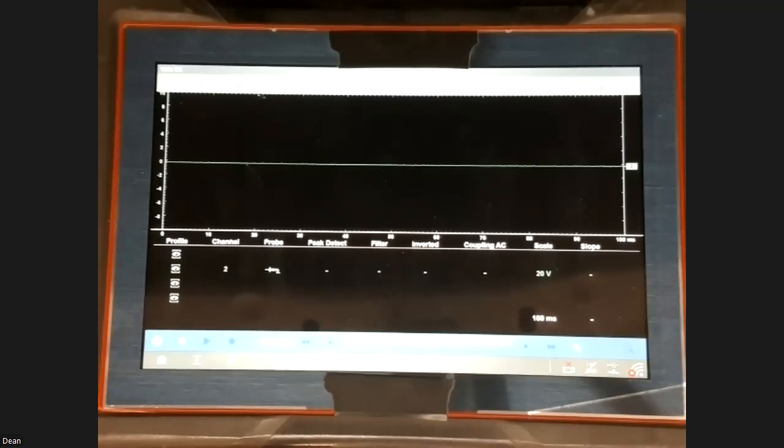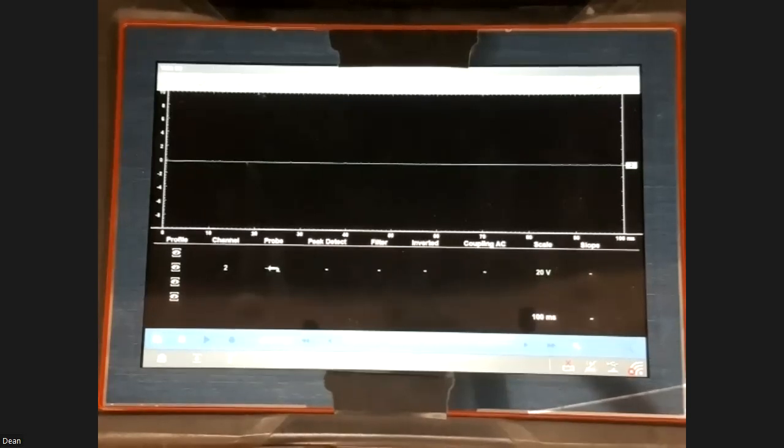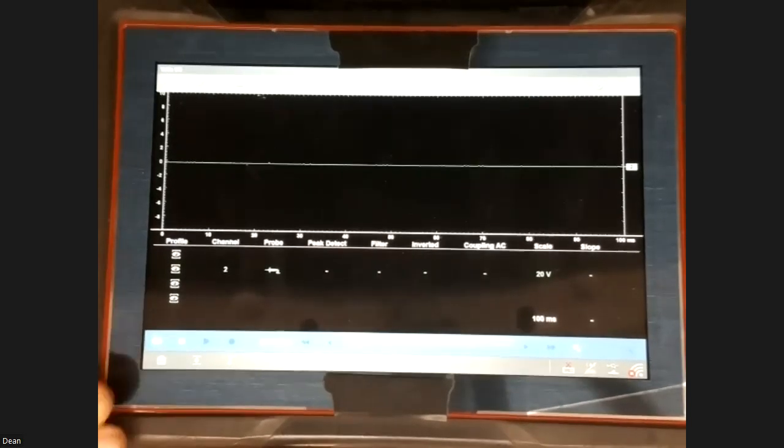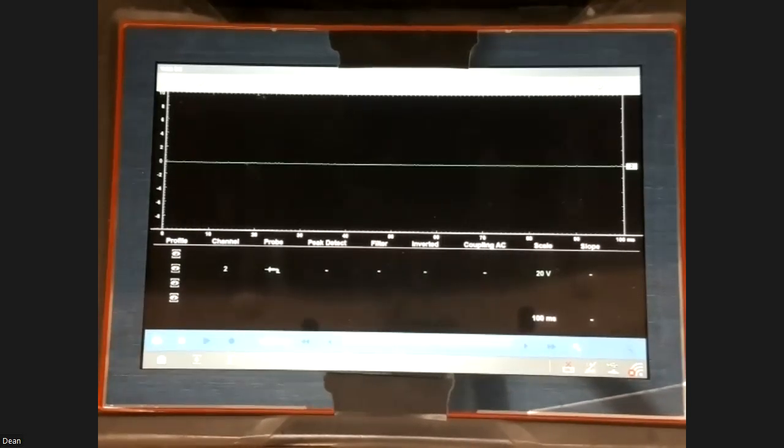I don't use a battery checker here at the shop. Not that there's anything wrong with them. My preference is to use an oscilloscope. That's what we're talking about today. I haven't really used a multimeter, unless I'm going underneath a dash and I'm looking at a voltage supply quickly. I'm not going to grab my oscilloscope to go underneath the dash and look at that. I'll grab my multimeter to check it.